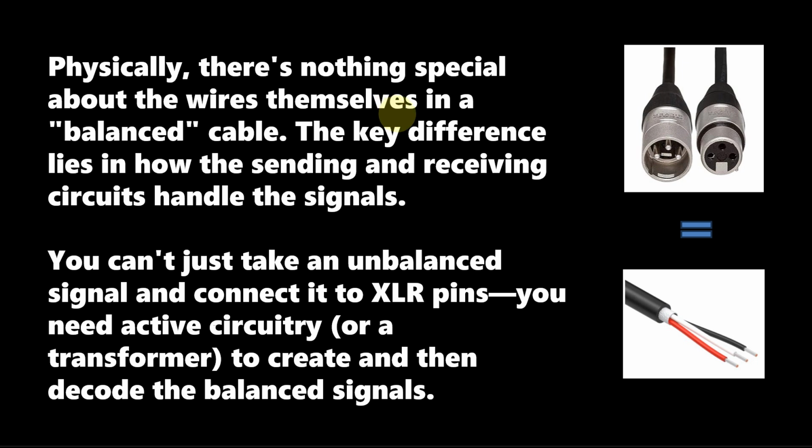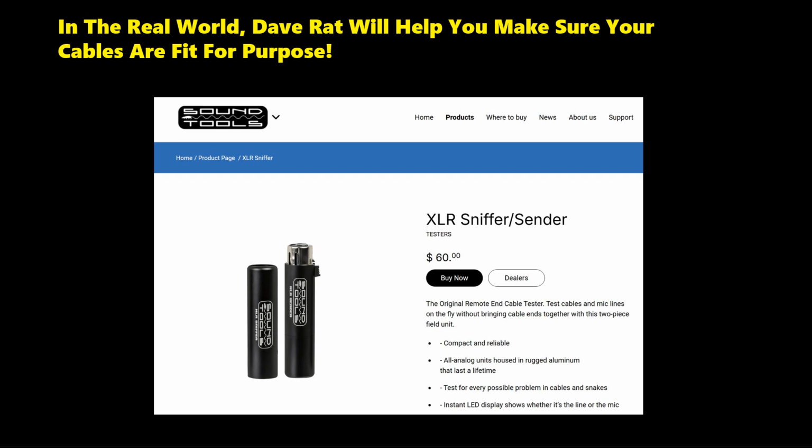But I do want to say, I still say there's no difference between XLR cables and regular cables. I mean, XLR is just a type of way they're pinned and putting an adapter. Balancing does not happen in the cables. Balancing can happen in any kind of cables. But that said, I don't want to say cables don't matter. They do. So, Dave's an expert in this, and he has a company that sells things that test cables. So, if you have an XLR cable and you want to run balanced audio, well, this thing will help you check out the cable to make sure you can actually do that common mode noise rejection or whatever.